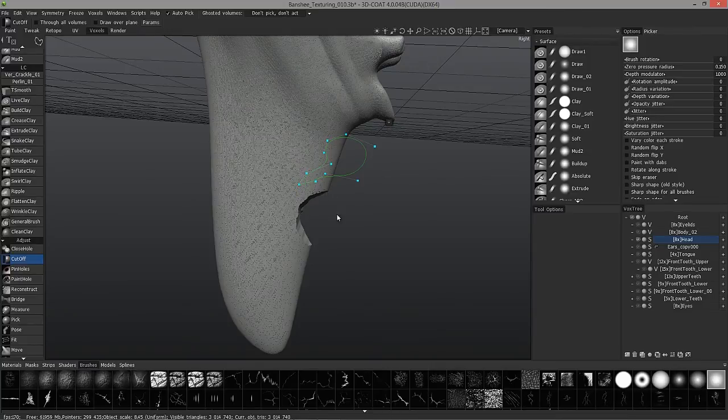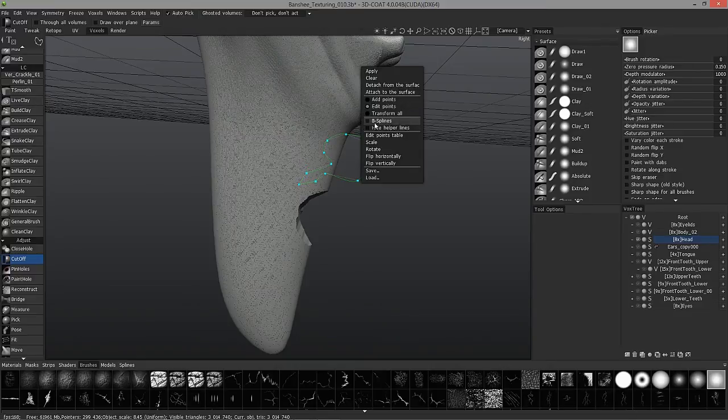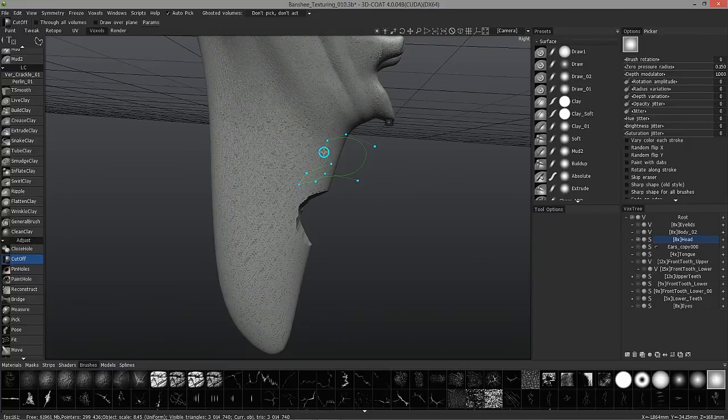Right click to sharpen the point. And it really depends when you're on this little toggle. If I have B-splines initially selected, okay, when I right click, it should sharpen. Let me take that back. With it unselected, B-splines unselected, one click will sharpen. But if it's chosen, okay, it will take 2 clicks to sharpen. So you're really going through a rotation: standard spline, hard edge, and B-spline. So when you right click, you're actually cycling between those 3 different options. Okay, so let's right click twice to make that a hard selection.